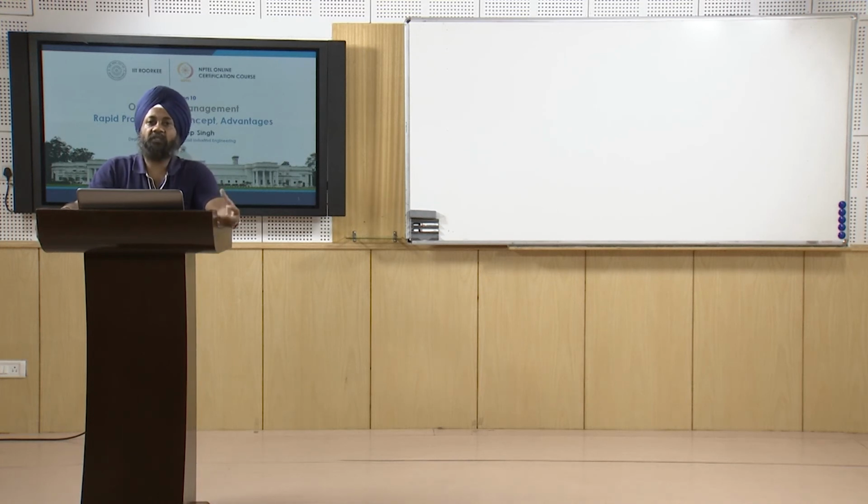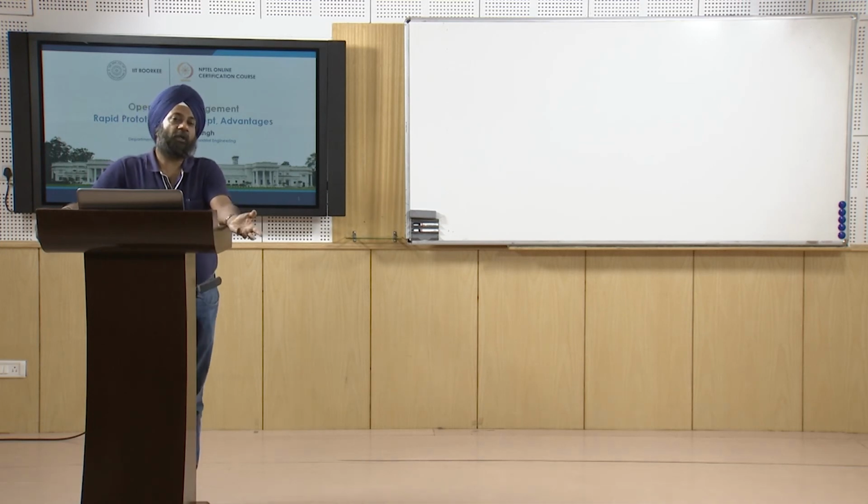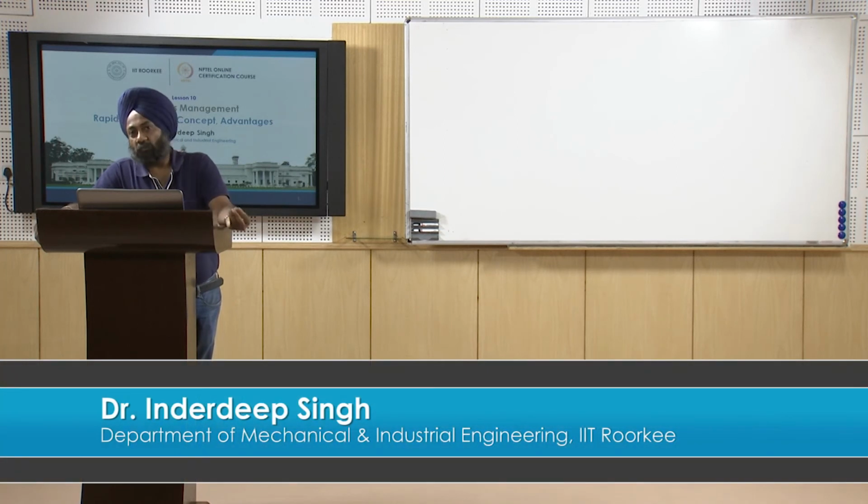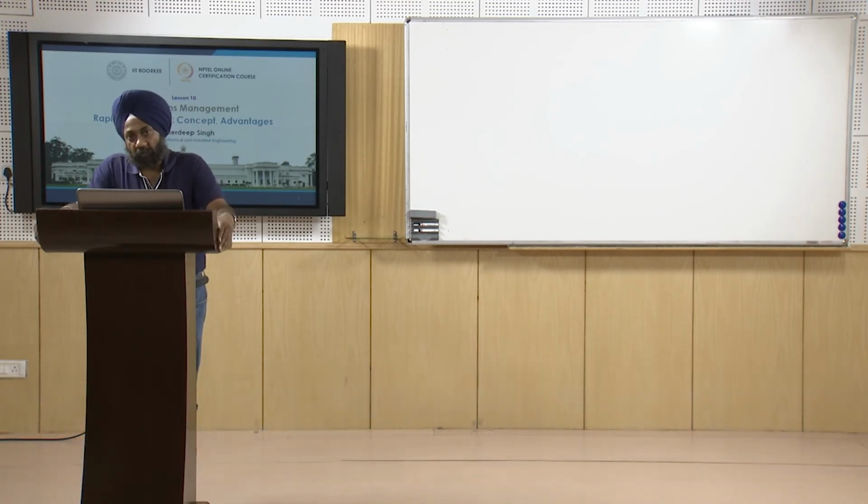The only requirement is the CAD file of the product. Once we have the CAD file, we can convert it to STL file. From there we can slice it, we can create the tool path and finally use any rapid prototyping technology to convert that product into its prototype. So, with this we come to the end of today's session on rapid prototyping, concept and advantages.